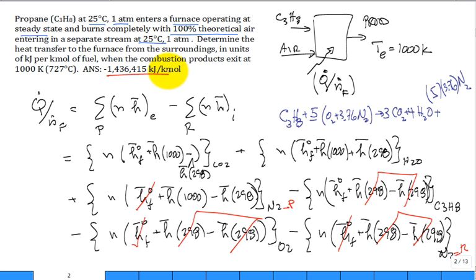Yes, sir. So if the dew point temperature was, or if the temperature at the inlet was lower than the dew point temperature, would there be condensation at the inlet? We have no water vapor in this air. This is dry right now, but yeah. You can calculate the dew point temperature. Typically it's 50, 60 degrees C-ish on the exit. And so if they're coming out at 1000, you're pretty safe that it's in the vapor state for the water. But if it's coming out at 298 Kelvin, well, no, it's going to have liquid.